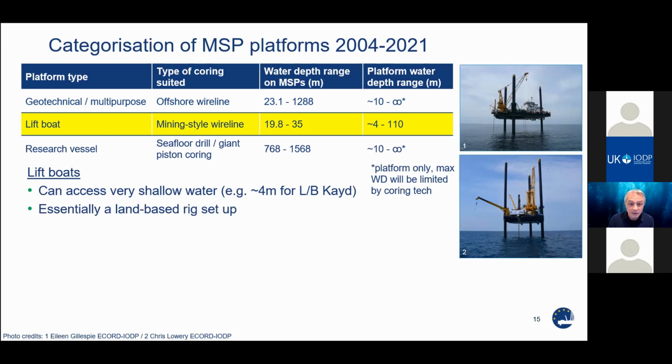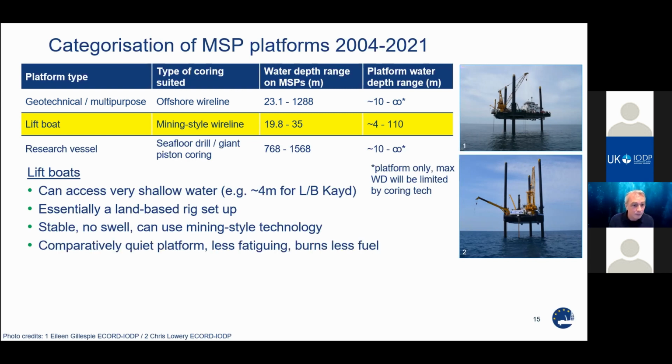These platforms are attractive for scientific drilling because they essentially offer a land-based setup. So when these vessels are elevated, there is no swell, and we can use land-based mining style coring technology, which, as I will describe later, brings many benefits for coring. They're comparatively quiet platforms, they're less fatiguing, and they burn less fuel. So lift boats, they have a lot going for them, but there are a few drawbacks.